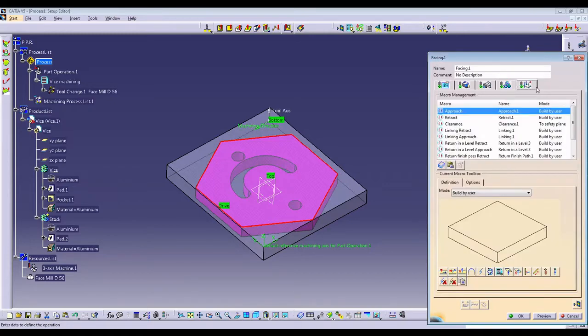We go to the approach and retract of the cutting tool, because our cutting tool will be put here as our starting point before cutting. We want to make sure that when the tool is being called here, it is called properly, it does not do a diagonal movement, and we won't hit the workpiece and damage the cutting tool itself.